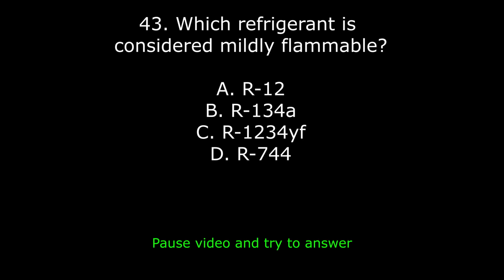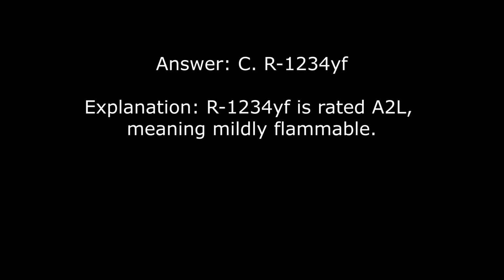43. Which refrigerant is considered mildly flammable? A. R12. B. R134a. C. R1234yf. Or D. R744. Answer is C, R1234yf. Explanation: R1234yf is rated A2L, meaning mildly flammable.